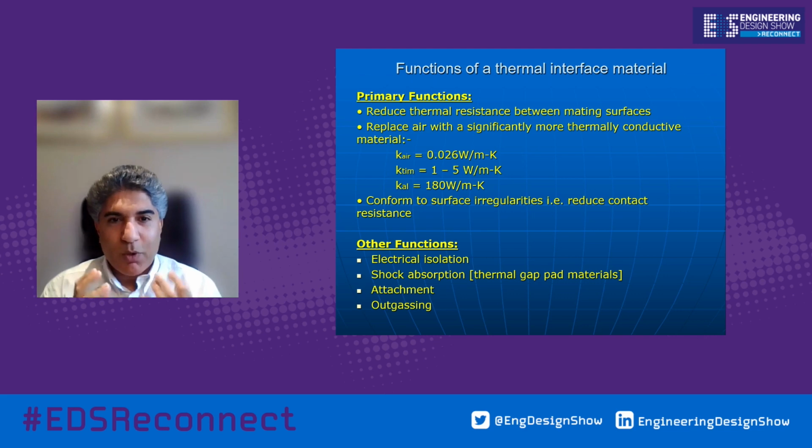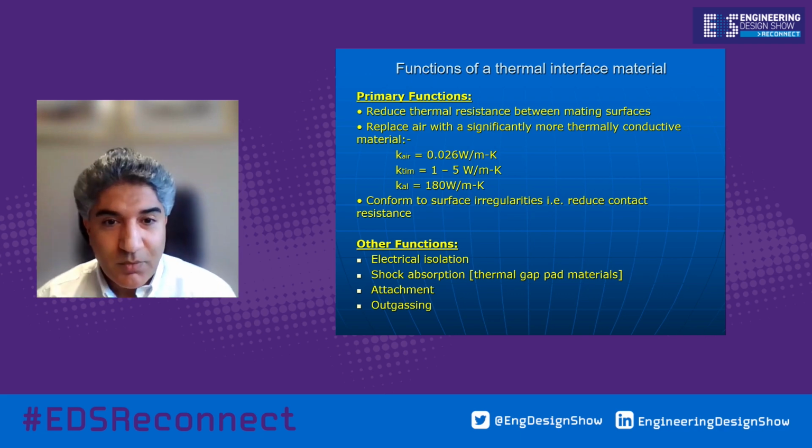Okay. In a nutshell, what we're trying to do with a thermal interface material is to manage the thermal resistance, to have the thermal resistance be as low as possible, to let the heat penetrate into the thermal interface material and let the interface, be it the core wall or the heat sink, do its work. Also, you have some machine finishes with nooks and crannies, and that's what the thermal interface material is going to fill in, those voids, so you get good heat transfer.